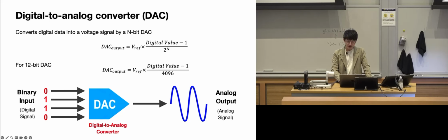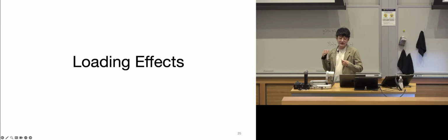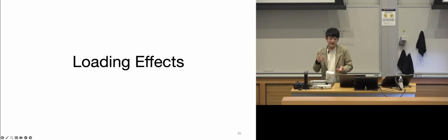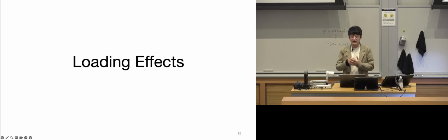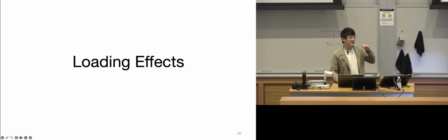Okay, cool. So before we dive into how exactly this DAC works on the hardware level, let's first introduce the concept of loading effect. Loading effect is when the output of the DAC is connected to a load, a resistor, capacitors, or an active circuit, etc. And these loads will typically draw some current from the DAC. So that will affect the DAC's performance.